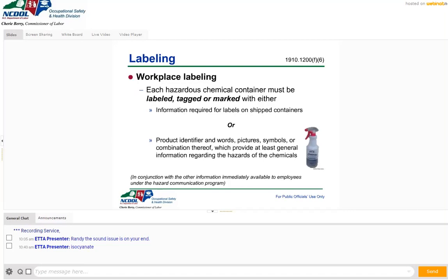So it has what this chemical is and the number for each hazard, and you would get those numbers from the safety data sheet. The only thing about those labels is that it has a personal protective equipment letter, like it might have B, the letter B, which I'm just guessing because I'm not looking at a chart right now. It might want you to wear safety glasses and protective gloves.